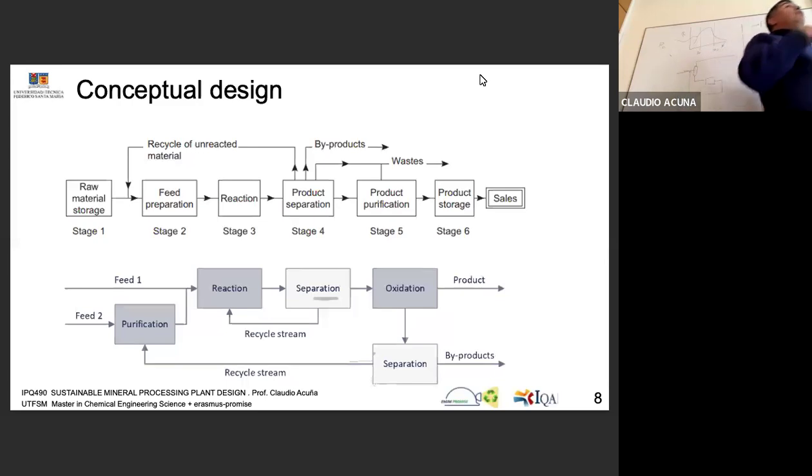In general, in flotation, in a good flotation, what is the probability of collision percentage? 3%. 3% is good enough for collision. When you have 20 microns, 10 microns for a 1 millimeter bubble, you have 0.001%.